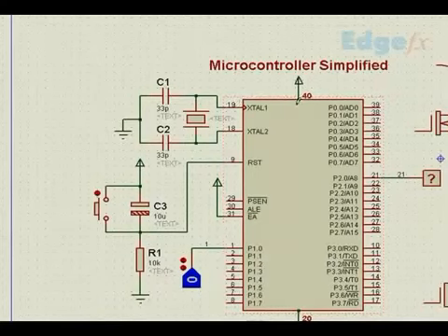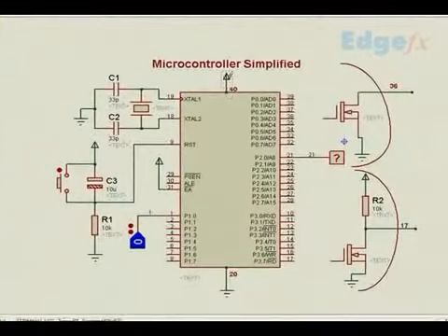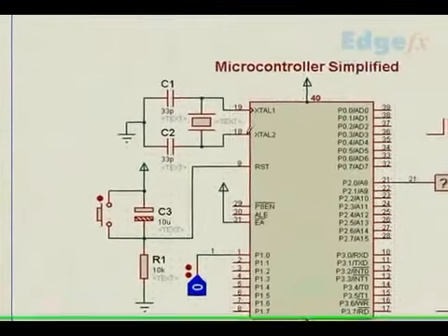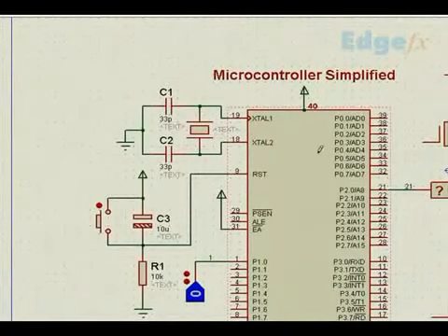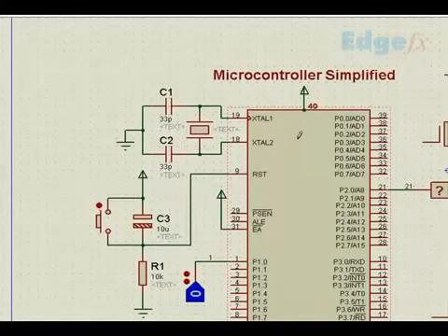In a standard 40 pin, the supply is 5 volt. We have to give 5 volt because this operates on 5 volt. We have to use some regulator like 7805 and give 5 volt here, and this is the ground pin, pin 20. Then pins 18 and 19 are meant for connecting a crystal. That crystal is meant for the internal oscillator to oscillate at that frequency. If this crystal is 10 megahertz, this will oscillate at 10 megahertz. If it is 20, it will oscillate at 20. Typically, a crystal of 11.0592 is used, and the internal oscillator will oscillate at that particular frequency.